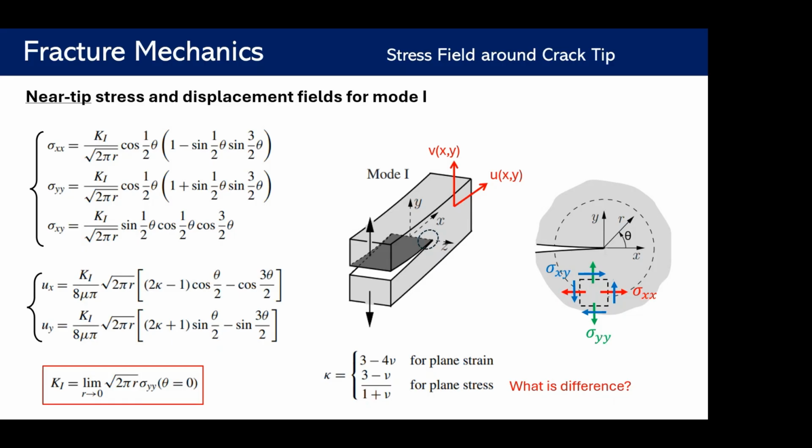On the other hand, plane strain is related to problems where the domain in the Z direction, normal to the XY plane, is extended to infinity. In geomechanics, in geological systems, you have a fracture in an infinite domain.